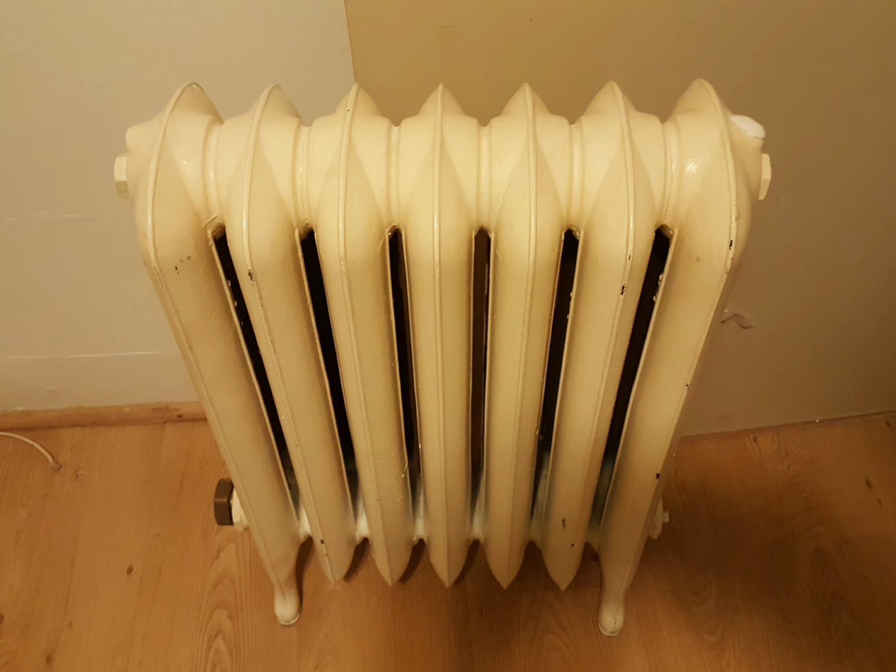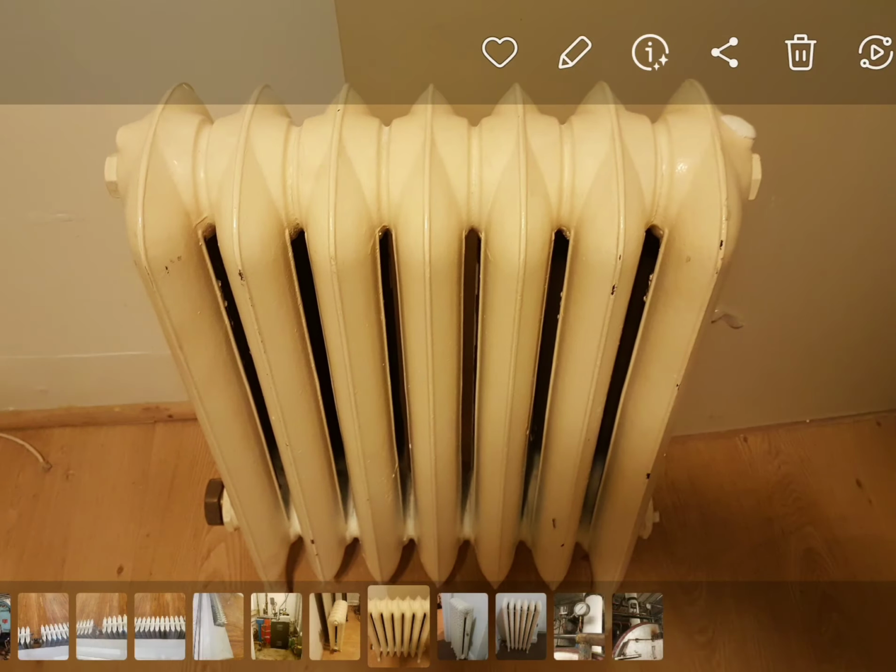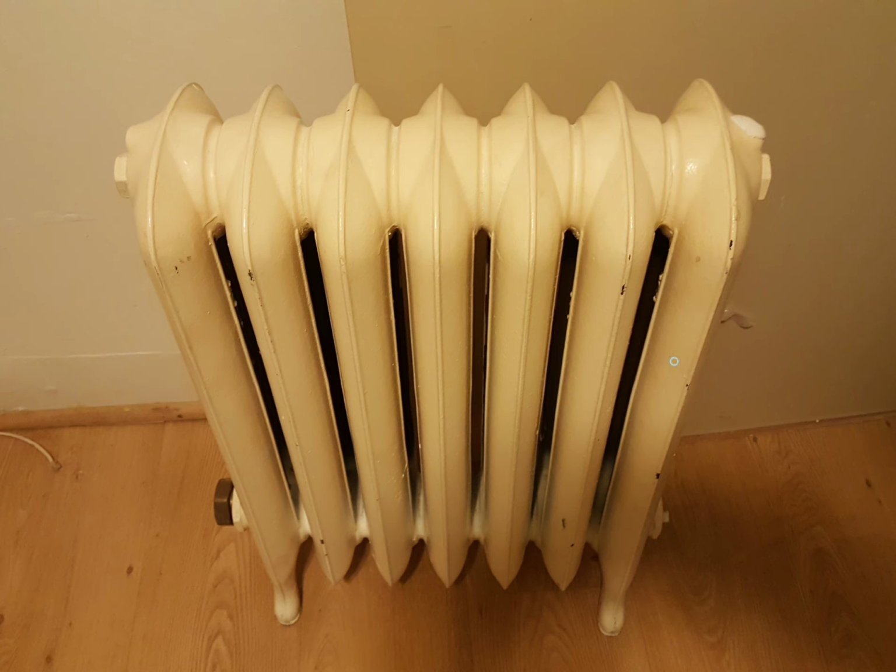In this particular situation, we're dealing with a small residential, maybe one or two family home. The way you're going to notice these things heating up, it's going to be from the bottom, the first section, making its way up to the top, all the way to the back, and then slowly making its way back down. Your air vent's personalities or characteristics are typically going to be, once it heats up, usually the whole bottom of the radiator. Usually by the time it gets down here, most of the radiator is pretty hot. So the air vent doesn't have too much venting to do.